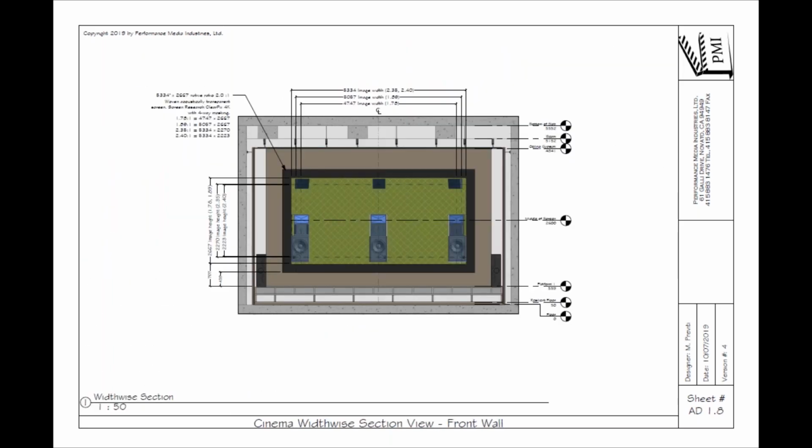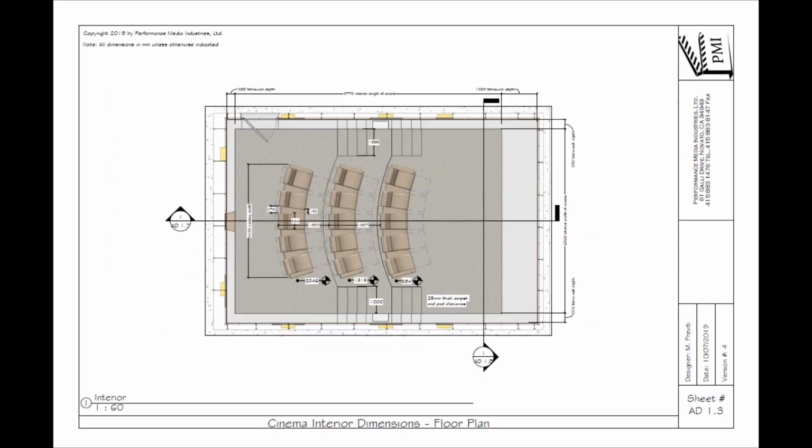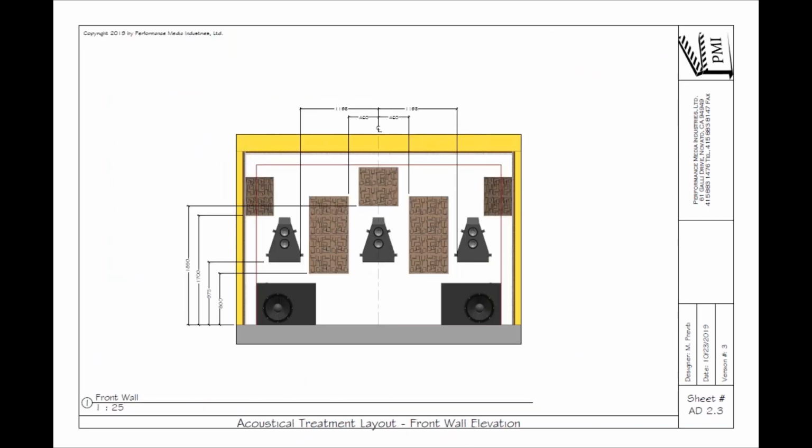Yeah. So one option, if you're building a whole baffle wall, like in this room, is the entire baffle is lined with 2 inches of what's called line acoustic or some other mid-density absorber. On a number of the other designs, let me go back to that. I've shown what we're putting, which is, there is not a baffle. This is the front of the room. There's an acoustically transparent screen over here, where these particular speakers don't need a baffle wall. Our speakers are built to go on a wall, and we're just putting absorbers, preferably low frequency absorbers, so as to not suck out too much highs out of the room in a useless way.